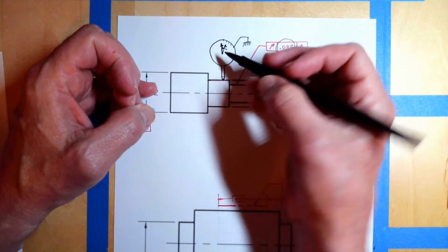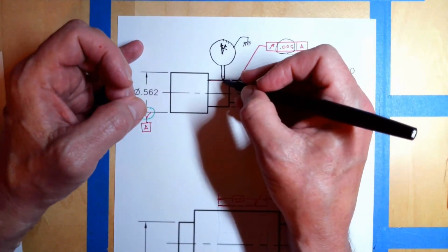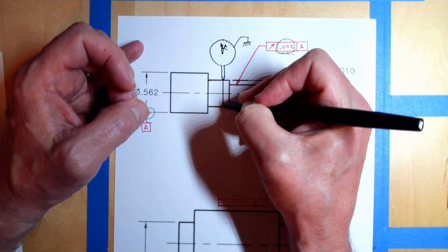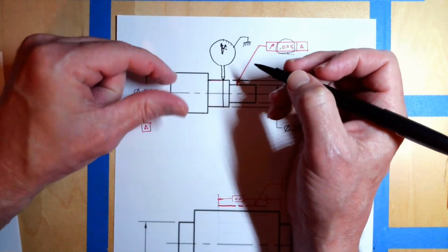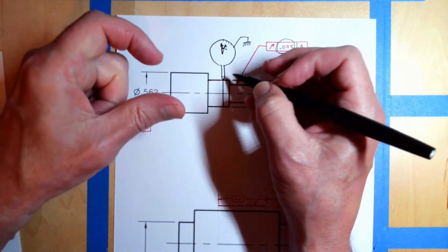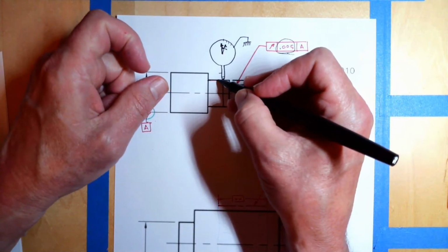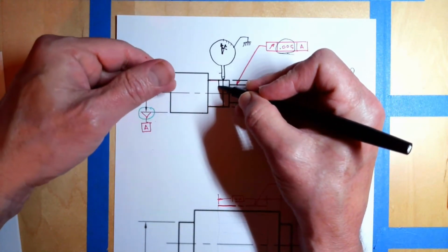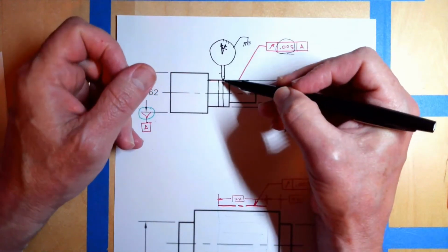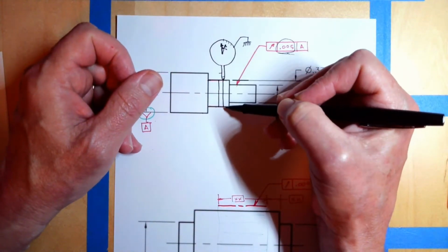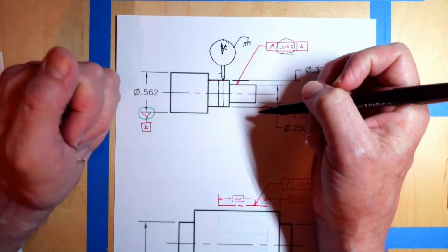All right. Now that's circular runout. So circular runout is when we measure at one point and we rotate it around, and then we stop, and then we move over here and we measure this point and we rotate it around like that. So you see what we're doing each time is we're tracing out a circle. And that's why it's called circular runout.